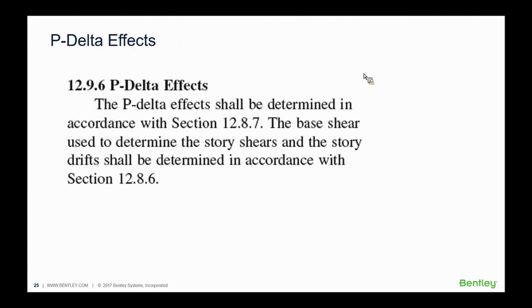Going back to our presentation, P delta effects. One of the challenges that practicing engineers are confronted with is to account for P delta effects even when carrying out a dynamic analysis like response spectrum. The challenge stems from the fact that response spectrum results are all absolute values, using which one cannot really carry out a second order analysis like a P delta.